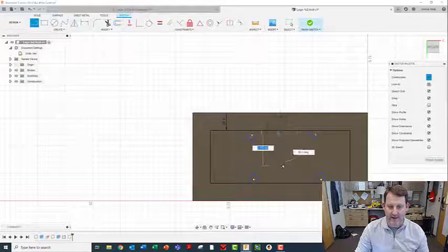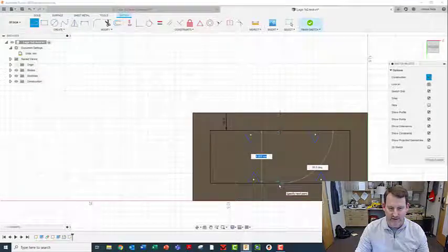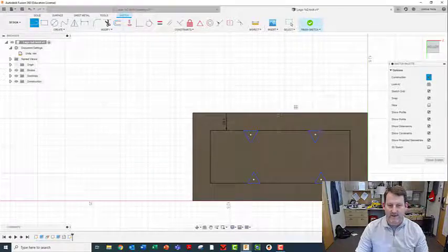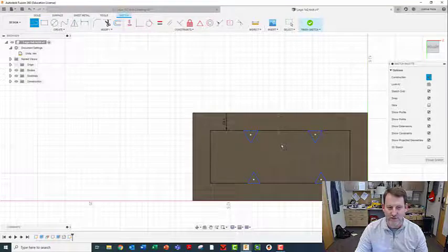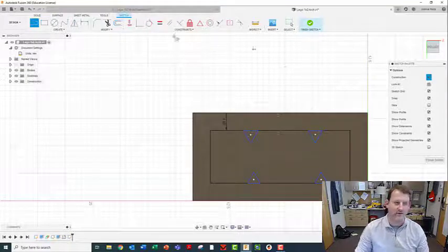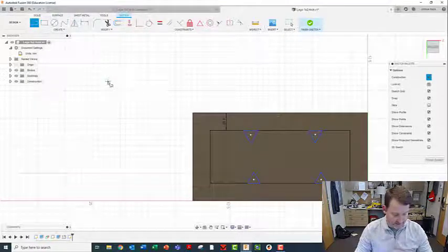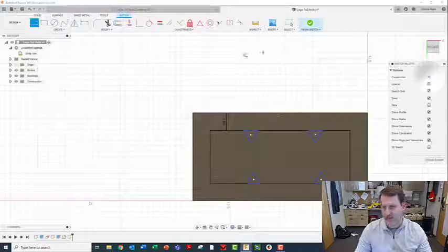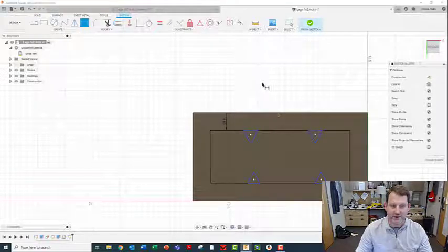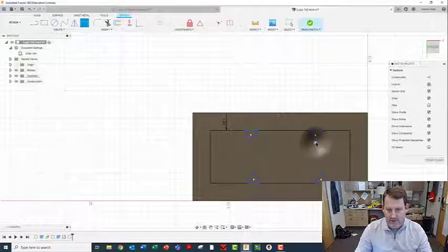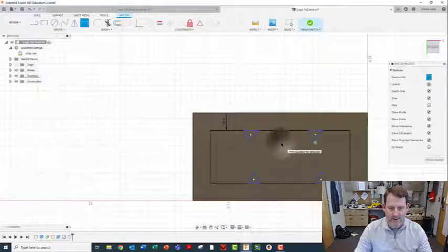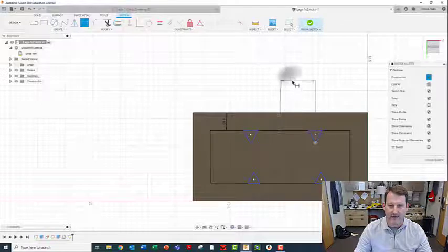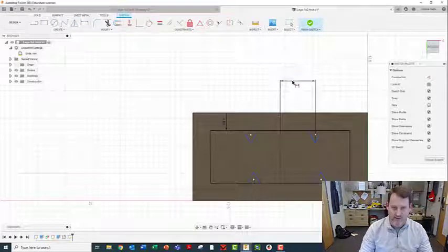I'm going to click on that and come straight across to 90 degrees. And again, I see I'm on the midpoint, and I'm going to click on that. That gives me the mid. And I want the top of my triangles to be 2 millimeters from that line. So next thing I'm going to do is turn off the construction lines. I'm going to hit the dimensioning tool, click on the top of, see how it got all white and glowy? And then click on this line. And I'm going to say I want that to be 2 millimeters.